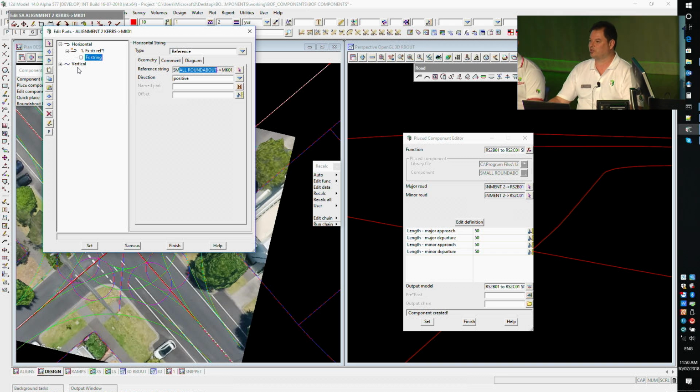Because with vertical geometry, you might have sag points, or you may be trying to introduce high points to make sure you get water that drains across major intersections. So this is the most successful way I've seen people using components. And this way too, it doesn't matter what 12D call their naming conventions in the component.